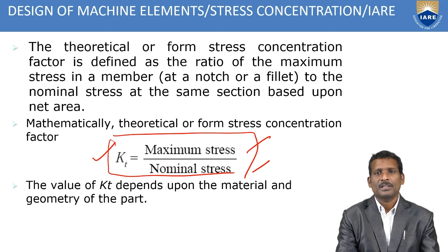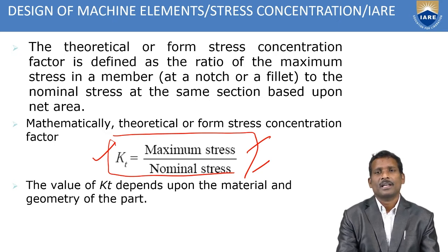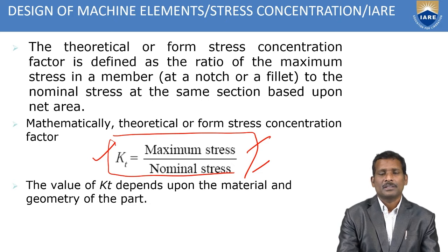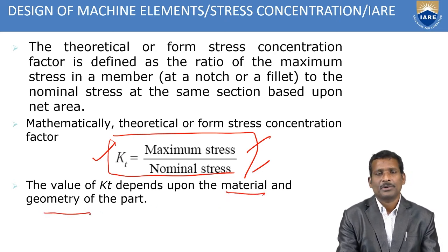But in irregular components, or whenever holes, notches or fillets are present, we can't calculate the nominal stress directly. Why? Because there is some discontinuity. So by using this theoretical stress concentration factor, we can calculate the localized stresses, where the maximum stress will occur in that particular region. This KT depends upon the material and the geometry of the component.